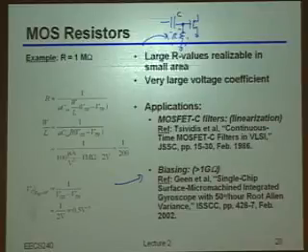Okay, so inside of those band gap circuits, you usually need some kind of resistor. Do you care all that much what the value of that resistor is? No, you don't, right? Because as long as things are kind of in a reasonable range, you'll still get the band gap voltage at the output. Okay? So indeed, these are just a few examples of places where even though the value can vary all over the place, you just want something big and you don't actually care all that much about what the precise value really is.